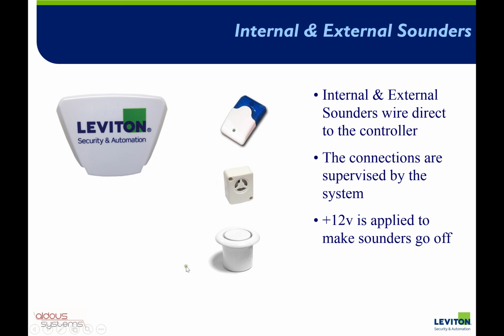This one's very good here. This little recessed one, size of a downlight. Pop that in the ceiling on the landing. You need to have 80 decibels to the bedroom door for smoke detection. So put that in the landing. And one in the hallway, and perhaps another one in the kitchen, maybe above the kitchen cabinets. You don't want to see them, keep them out of sight. This little guy is also very small and quite handy just to wire into maybe even inside the cabinet, so that there's a tamper on the cabinet. Someone opens the door, then it'll sound very loudly.